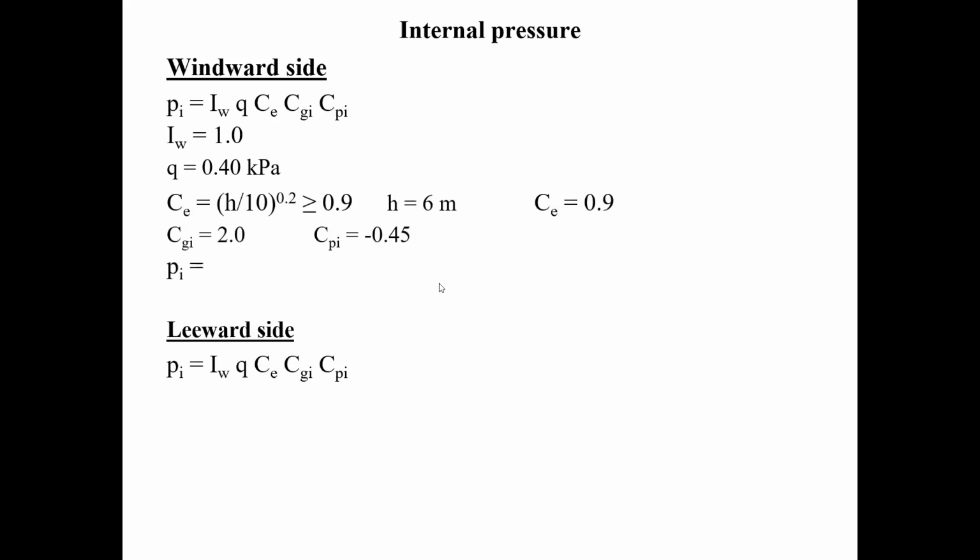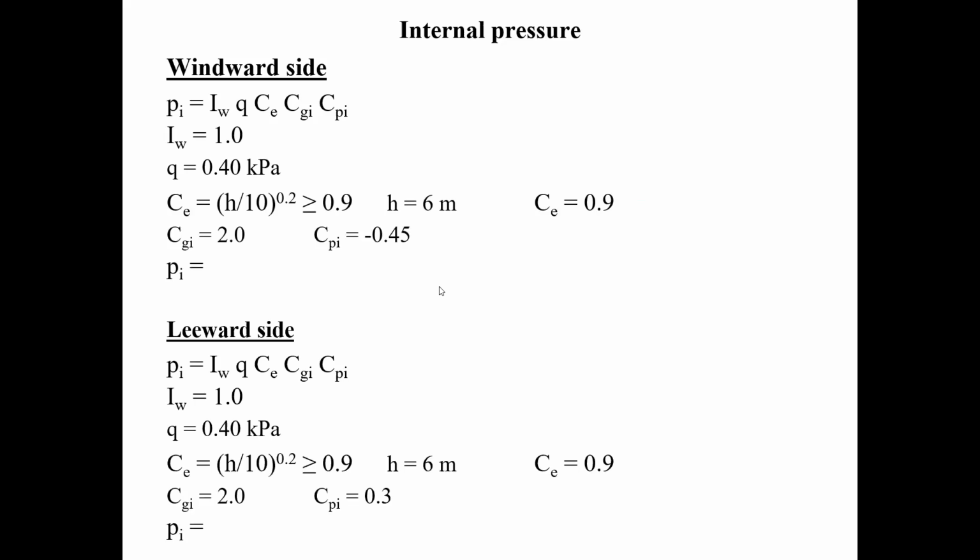Okay, and there you go. So now you've got all the information, and just like we have done in the lecture, you can go and calculate your WF, you can calculate your PF, and then you can go for case number 3, case number 4, and check to see if your PR and your WR for a 2x6 is okay for load combination number 3. If it's okay for load combination 4, of course, then you've designed the studs for the exterior walls. Or you've confirmed that a 2x6 at every 24 inches would be sufficient to support the gravity loads and the wind loads. Yes, go ahead.